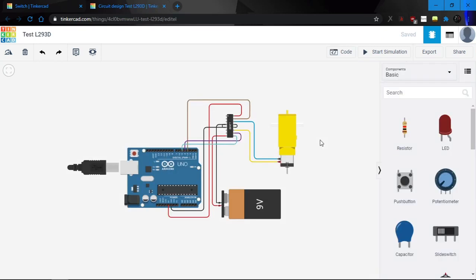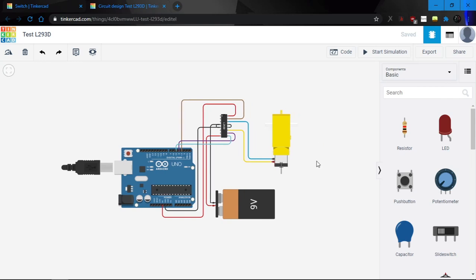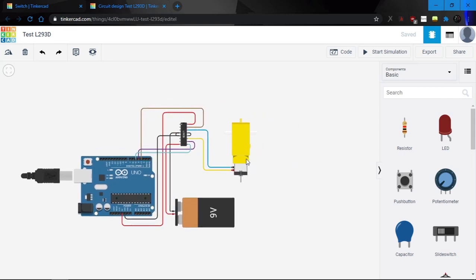Okay, lastly you will learn how to use a motor driver. When we use a DC motor, it only has 2 pins, which control the direction. If we only use these 2 pins directly with the Arduino, we cannot control the speed using code, and the speed will depend 100% on the power of the power source. That's the first issue.